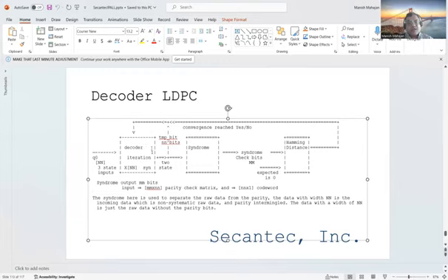You can do 50, 100 iterations, but in every iteration, it will calculate the syndrome and check whether the syndrome is 0, by comparing the syndrome bits with the 0 bits using the Hamming distance calculator, and that will actually circulate through into the decoder.